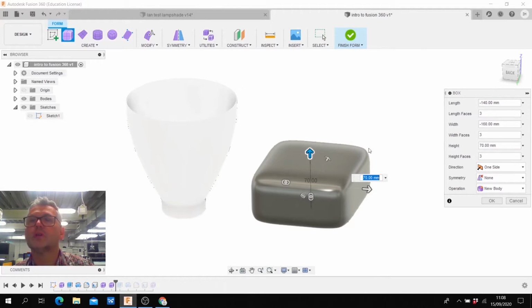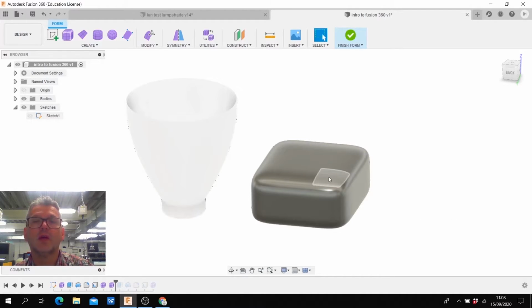And there's my box, and I can have as many faces in there as possible. I'll show you the faces once we click OK. I've got 3 faces, and I can actually manipulate this now in a much more fluid way. I can manipulate using a line, using a point, or a plane. I'm going to choose a series of planes. I'm going to click Shift and just click these 3 planes.